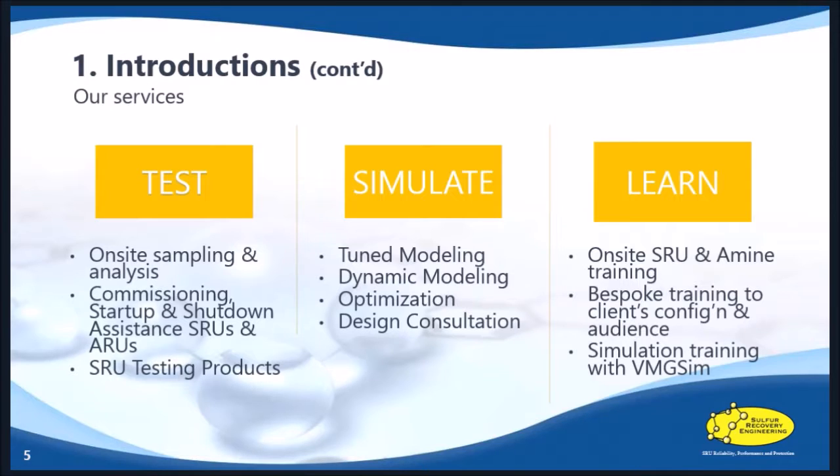VMG uses SRE's last 15 years of on-site testing data for different kinds of sulfur recovery units and different configurations, and VMG incorporated those data to create SRE VMG correlations. So by using the VMG SRE model, we can create a model which predicts more accurate results that match the practical performance of the unit instead of a just theoretical model.